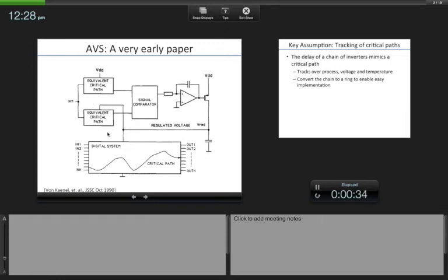And the way the author proposed to do that was to have a digital circuit whose voltage comes from a voltage regulator. So this is a simple voltage regulator circuit where you have an external supply, but the supply which is actually given to the circuit comes through a drop out across this device, and this op amp sets this voltage such that it is a regulated voltage.